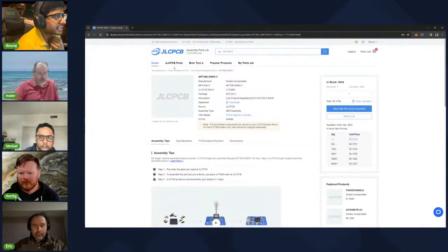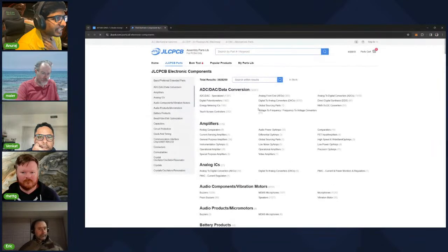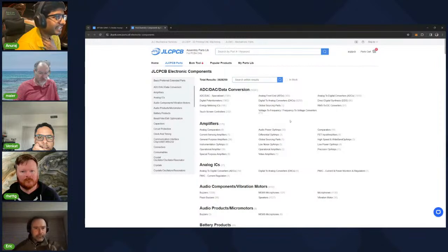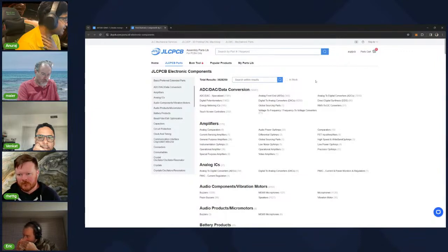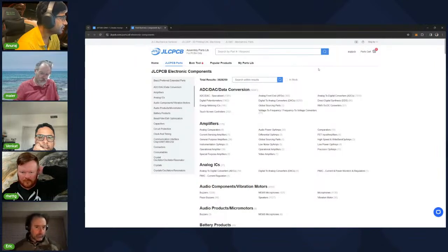Yeah. So the first thing you have to do is, after you sign in to the JLPCB website, go to their JLPCB parts. This is their sourcing place. You can find the parts you want in here, and then you select them, and they have their own part number for it, because that is required when you are giving the file for manufacture. It requires 2-3 files specifically for manufacturing: the BOM Excel and the positioning of the parts in the BOM. So these 2 files need to be there when you are giving it for manufacture.